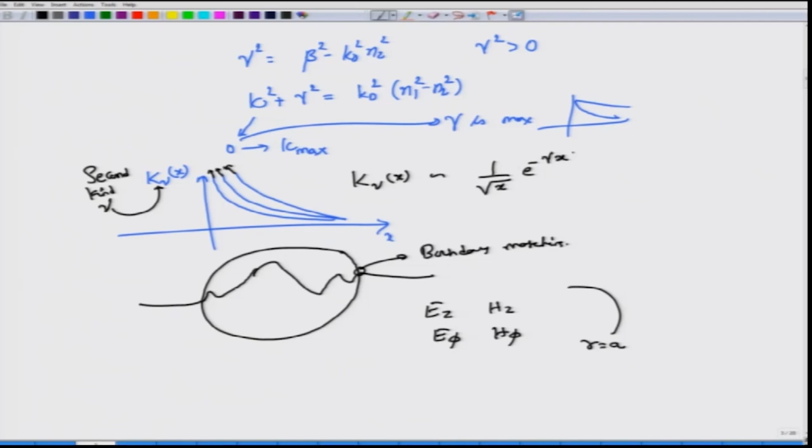This gamma need not be the same gamma, but it could be the same gamma in case you are applying these equations to fiber. So, you have these 2 types of Bessel functions. Just for the record, there are other categories of Bessel functions, some of them go like this. These are clearly not allowed solutions, because they are not going out. So, we have only Bessel functions of first kind of order nu and second kind of order nu as the solutions for Ez.